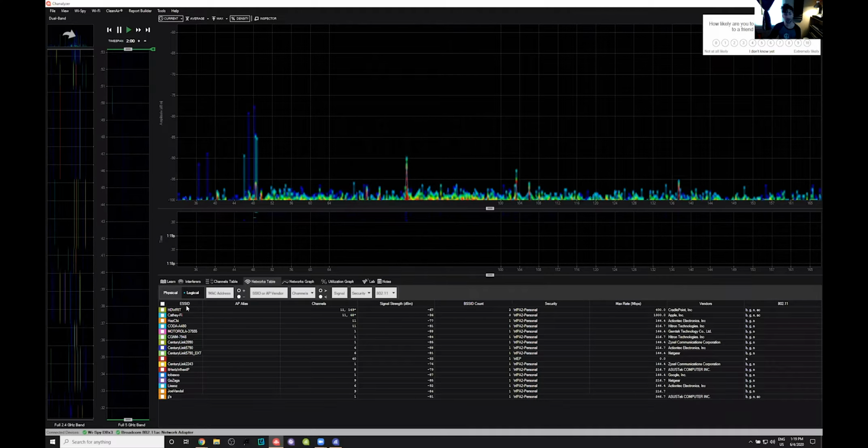And so I learned my lesson to hardwire my access point when I'm messing with interference and signal generators. And so let's just say this is intermittent. It's talking quite loudly over here. And if I move my time selector bar up to the last 30 seconds or so, you can just see bright red, right? This is a significant interferer. I'm going to say it's intermittent, so I'm going to unplug it for the moment.